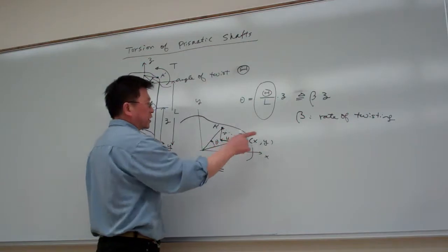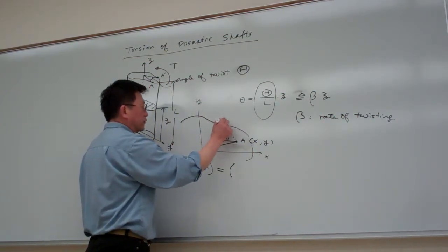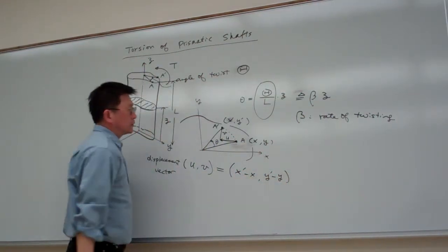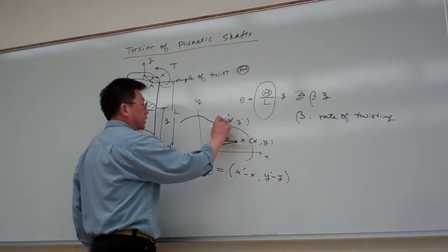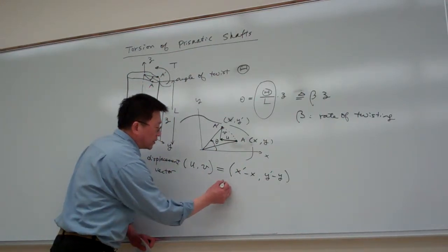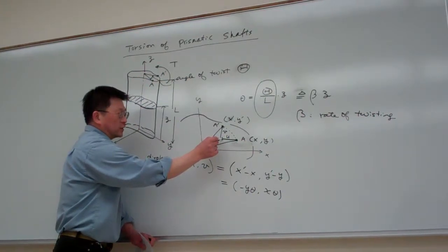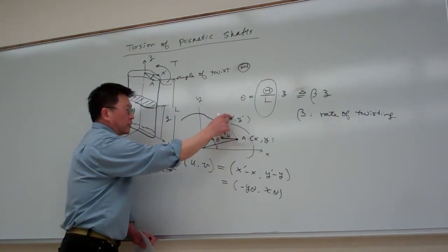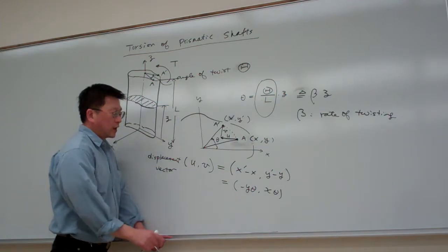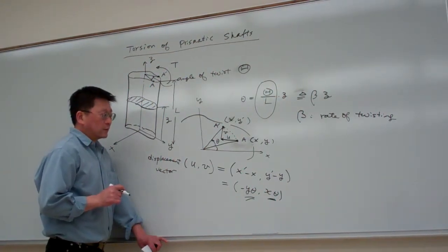With this in mind, last time through the rigid body rotations, you can determine the difference between x prime and y prime. You can formulate x prime, and that is what we did last time. Basically this can be related to minus y theta and x theta. So the displacement component in the x direction, through careful arrangement like this, is equal to minus y theta, and v is equal to this one. To see how to obtain this, please refer to our lecture notes from last time, or the handouts, where we provided the details.